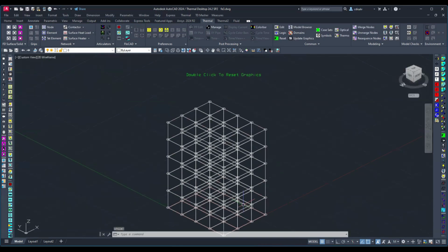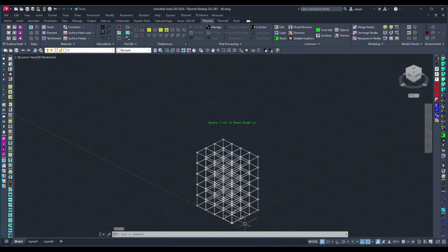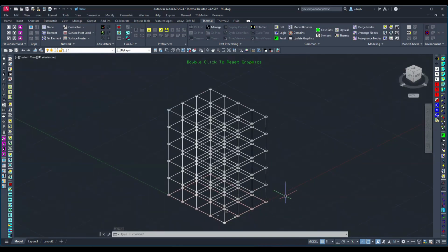and okay that, you can see that we've got a lot of clutter if we're going to look at different angles of the model. And like I said, that's just the interior of the model. And we're going to want to hide the visibility of that because when we go and run a case, the way that Thermal Desktop runs, if we get too many graphic features, it could really bog down the program, especially if you have a really large model.